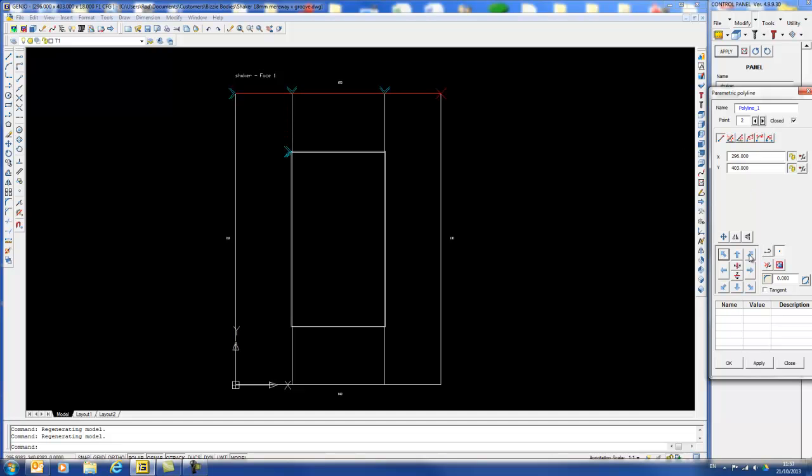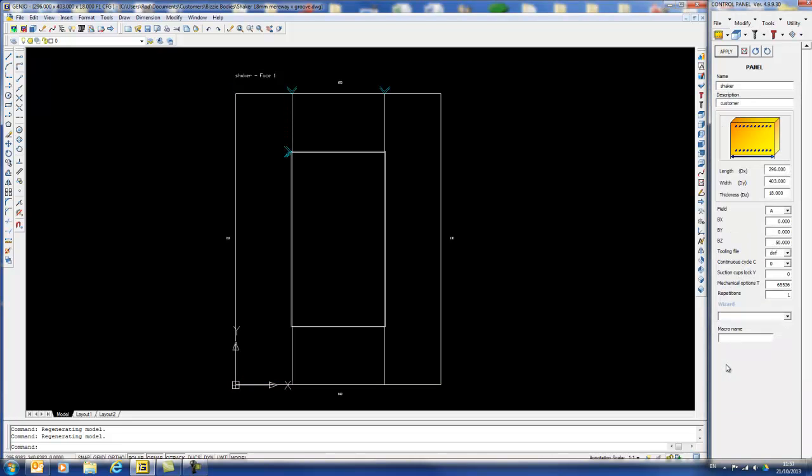We're now at top right. I select top right. It's now always at dx and dy. Point 3 is at the bottom right, so bottom right. So it's always dx and it's always at y0, and then the bottom left is at the bottom corner, so I can click that, although that's where it'll be anyway. So I can OK that one.